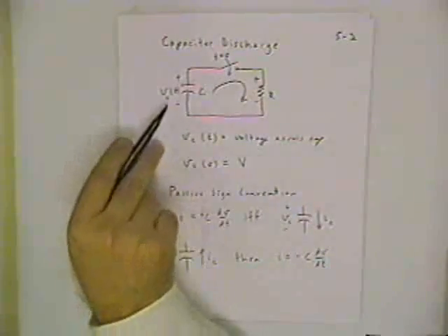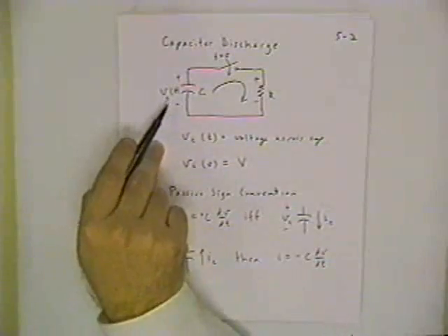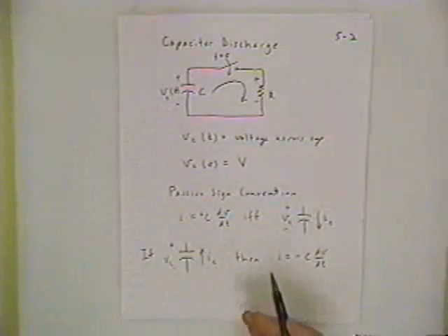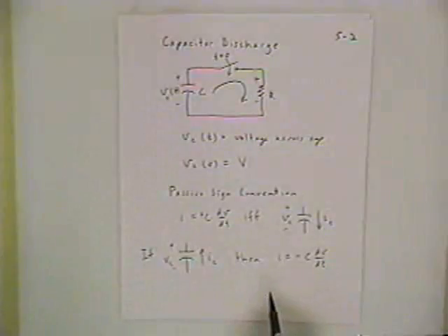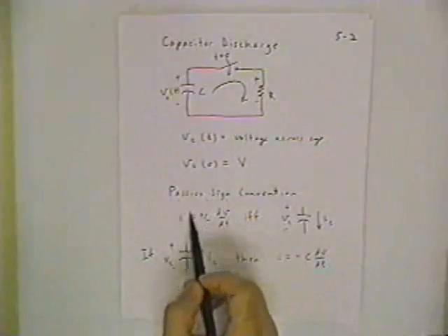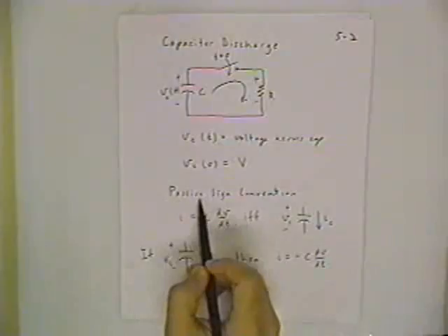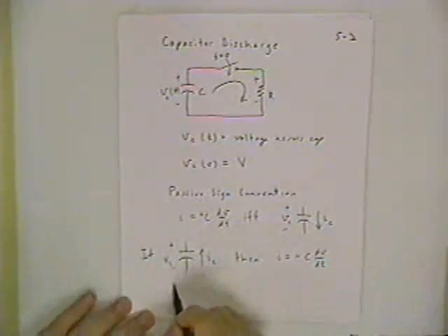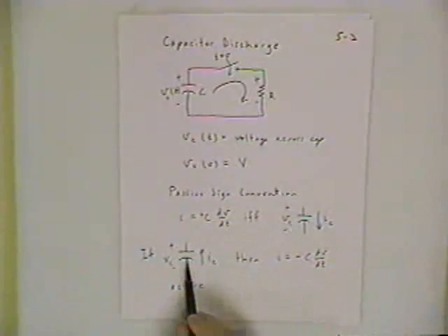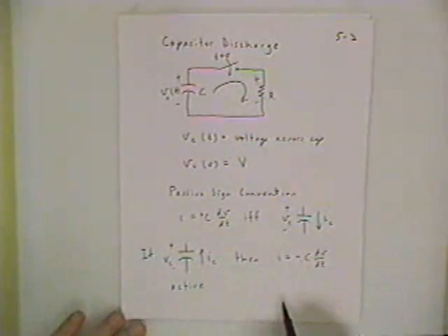The capacitor is acting temporarily in this case as a source of energy, and therefore we need to have our power expression P equals VI match up correctly with the right algebraic sign. So that's where this name comes from. It's a positive sign in the linear model if the capacitor is acting like a passive element, but in this case it's acting more like an active element.